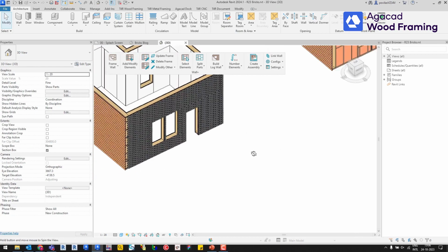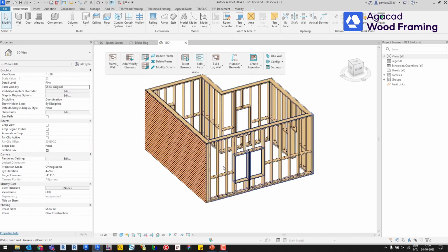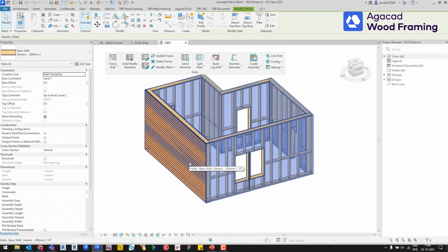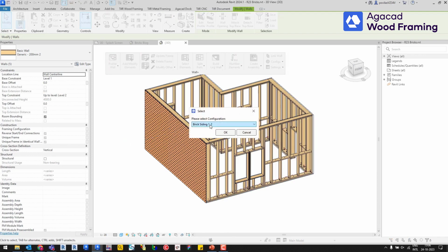So right over there where the brick cladding meets the timber cladding, there's that corner where you might have to adjust the configurations and perhaps some of the type parameters for the brick family. So that corner can be resolved with adjustment in the configurations and type parameters.